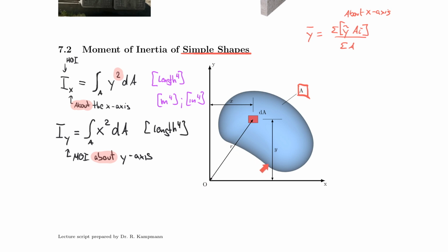But because you're dealing with an area, or the potato chip, and not the entire potato, this is not a three-dimensional body. Because it's not a three-dimensional body, this would not be Iz, although a lot of people call it Iz. But it's actually better called J-naught, which is the polar moment of inertia.